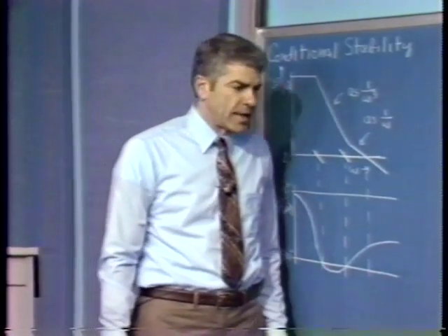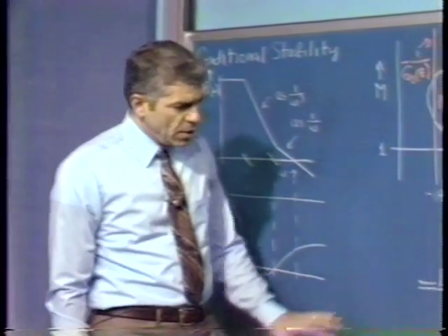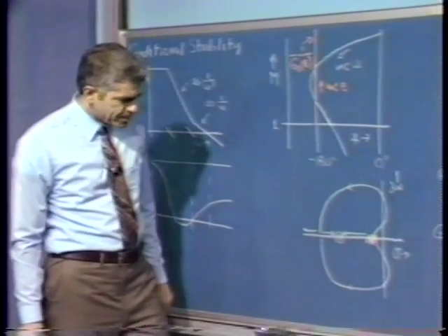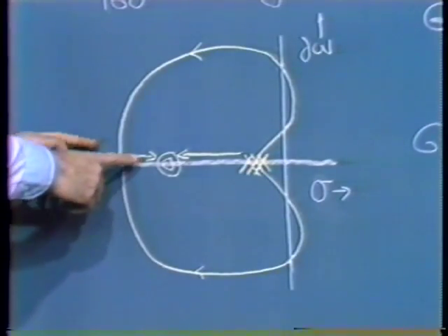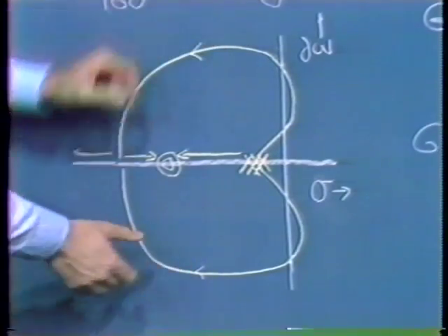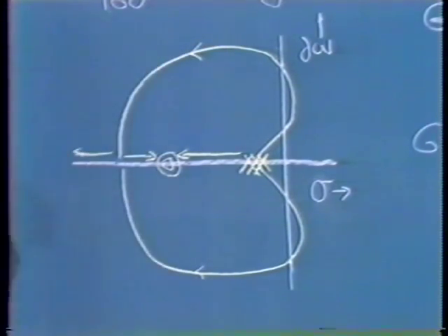Again, we can look at the same process from a root locus point of view. We assume that we might start out with a system design so that all of our poles lie in the left half of the S-plane. However, as we increase the amplitude of the signal at the input to the nonlinearity, the loop transmission magnitude, the A0 F0 product, in a describing function sense, drops.